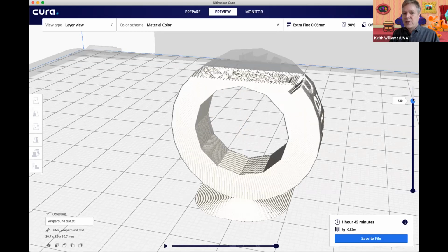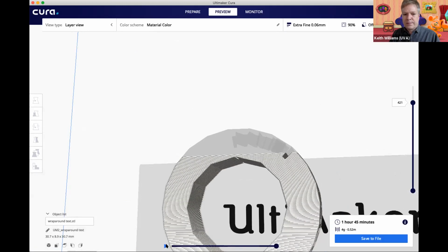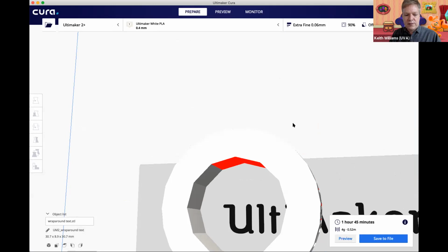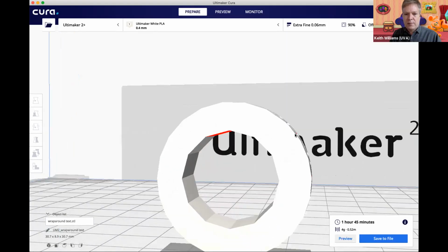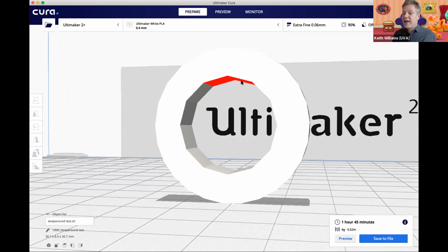The other issue that we have here, if you simply rotate this thing and look underneath, so let me stop the print simulation and just move it up like that. You can see, I made some reference to some red there. What's the red here? That is unsupported material. So that may be a bridge too far, right? If you start printing, we probably can print all of this fairly well, but when we get up to this point, now the print doesn't have any support underneath it.